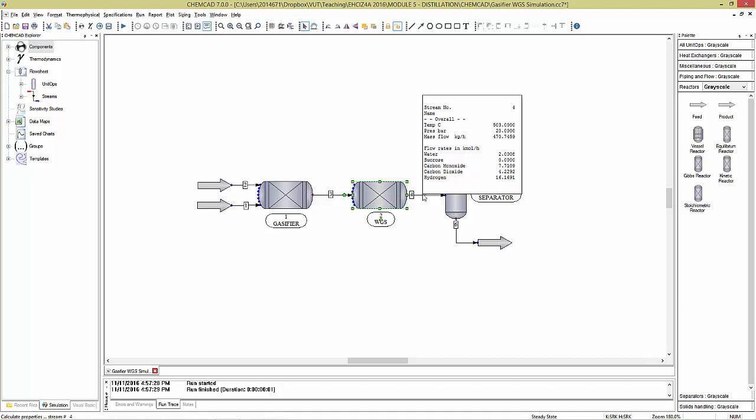Because again, remember, the methanol synthesis reactor is not going to be a 100% conventional reactor. It's going to be a kinetic reactor, which means that it will have a specific conversion type to it. In industry, I know it is usually around 20-25% per reactor, the conversion that you get for methanol synthesis. So you will still have a lot of gases that you have to recycle.